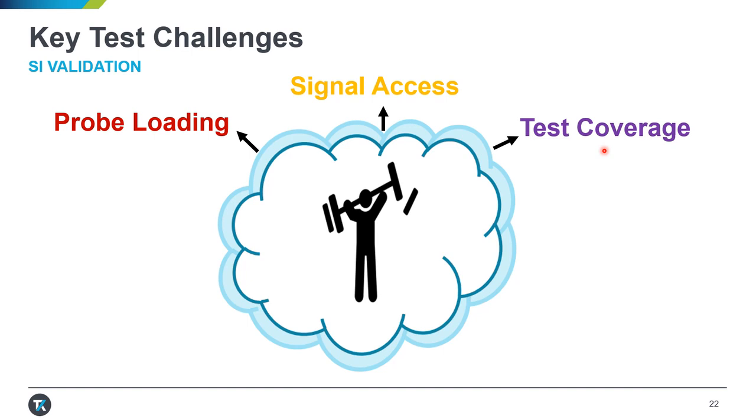But as a matter of fact, almost 80% of memory usage in a smartphone happens to be in the mid-speed range, which is typically between 800 megabits per second and 1600 megabits per second. I mean, think about it, right? We don't always watch a video or play games on our phone. I hope not. Typically, we are checking email, texting, browsing, reading news, and so on, which doesn't require max data transfers. So it is critical to make sure that the device and subsequently the system is tested for the above new modes.